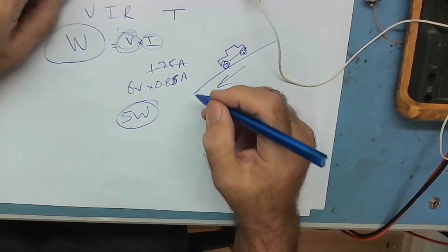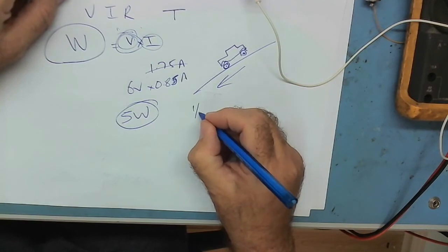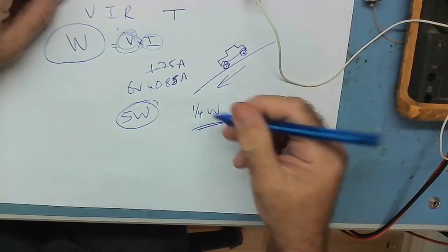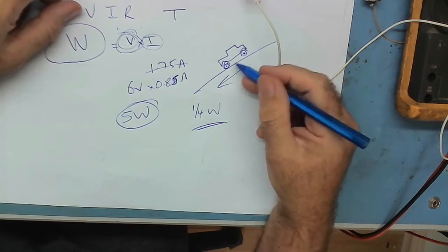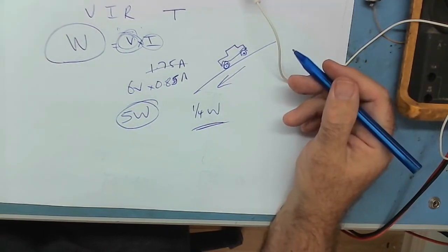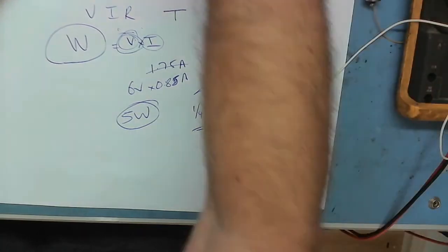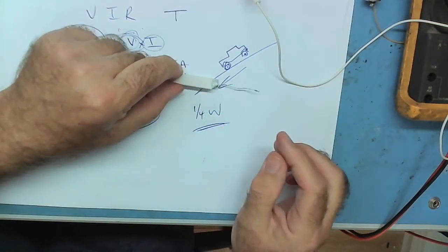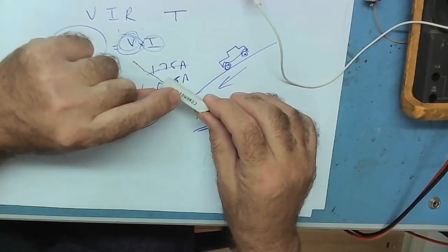And that resistor I used was like a quarter watt resistor. So this did what your brakes did. The brakes weren't powerful enough. You come down the hill too fast and the brakes just burnt out, and that's why that resistor just fried. And that's why you have resistors like this one. Big chunky resistors, yeah? Because this is a 10 watt resistor.